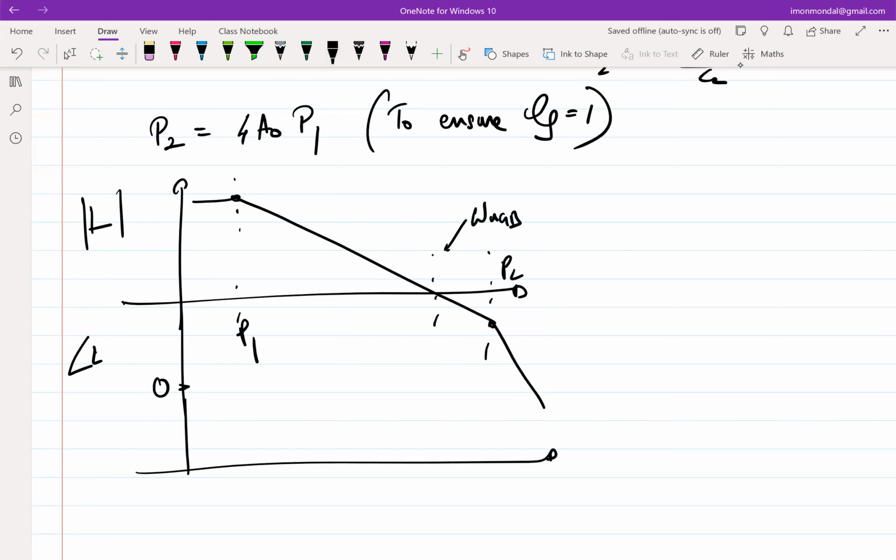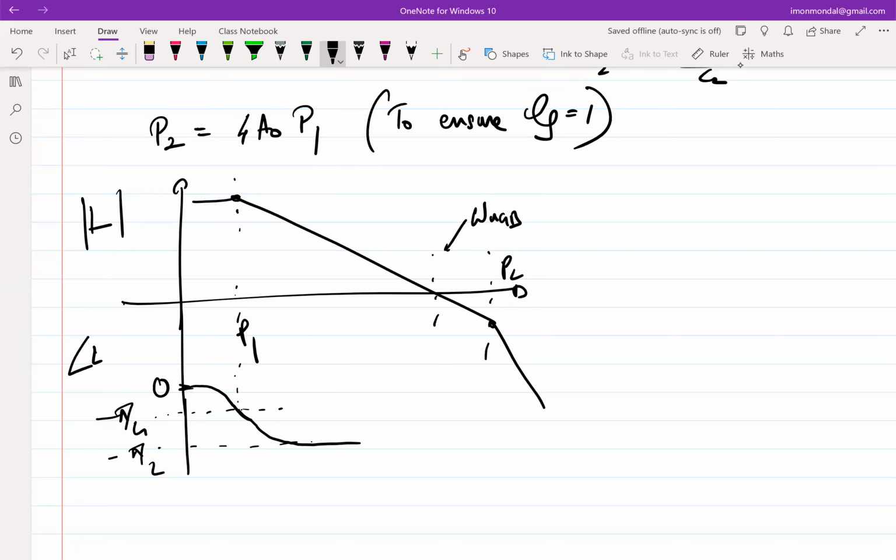It should end at -180, but before that we have two poles, right? It starts from 0, then at P1 it drops. What will this angle be? -pi/4. Then it goes to -90. Then it will drop further a bit more.